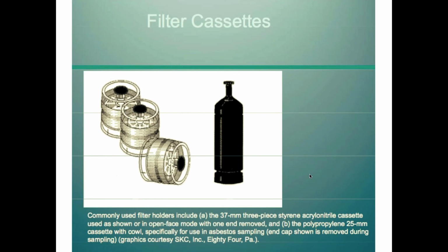So we have this filter. The filter is very, very thin and very light. Now you're going to pull quite a bit of air through it, at a medium speed, not that slowly, not fast. So the problem is that you could damage this filter as you're pulling air through it. So in order to keep it from getting damaged, you have another cotton filter, which is a backing. This is pretty rigid. You'll see this is pretty thick. Why is that there? That's just there as a backing, as a support for this filter.